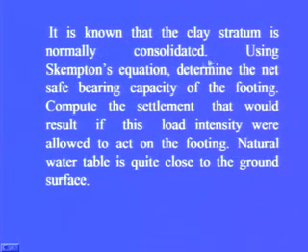It is known that the clay stratum is normally consolidated. Using Skempton equation, determine the net safe bearing capacity of the footing. Compute the settlement that would result if this load intensity were allowed to act on the footing. Natural water table is quite close to the ground surface.